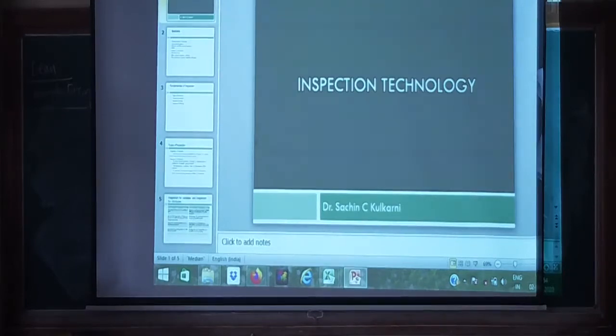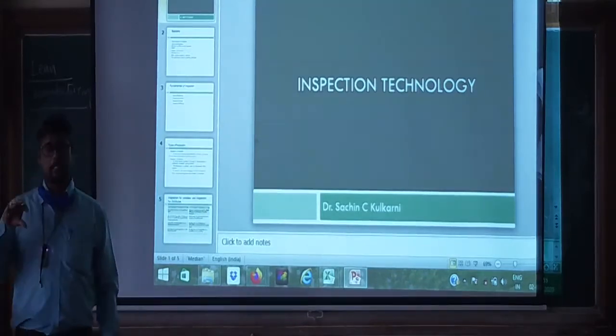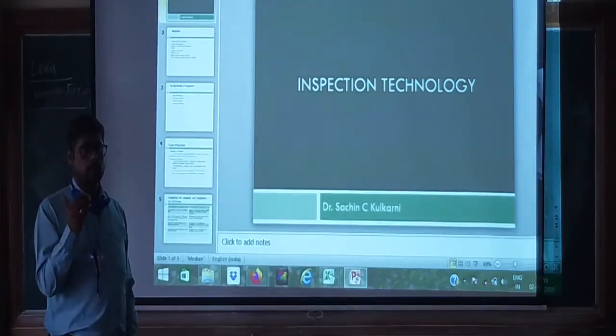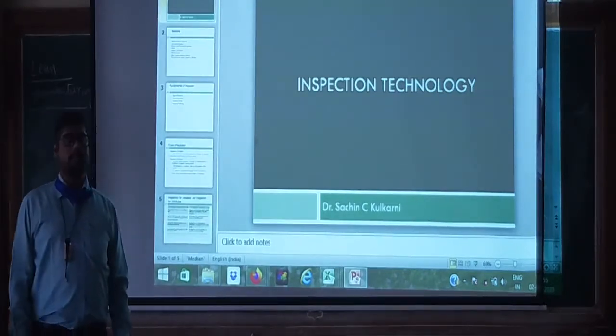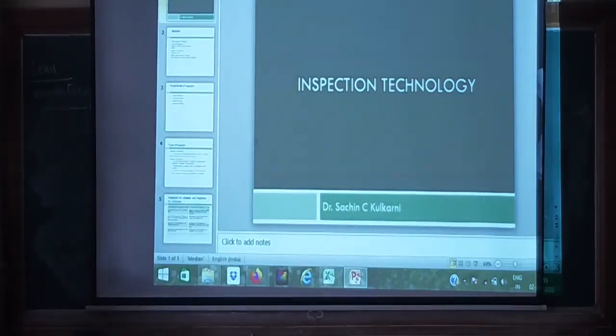And in the PQ chart indicating the most appropriate measurement equipment as a function of part variety and part quantity, we use part variety and part quantity with the help of CMM and other coordinate measuring machines. So: conventional measuring inspection and the coordinate measuring machine. Usually in contact type inspection, for 2D inspection we use a TRIMOS, which is a company name, while CMM is 3D inspection. For 2-dimensional inspection we use a micro height gauge. So TESA micro height, TRIMOS.